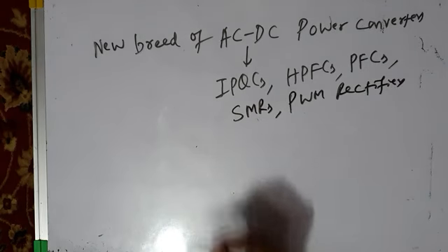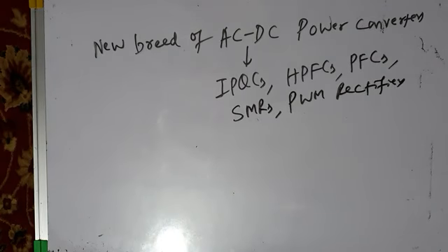All these converters do not use SCRs largely. They use modern self-commutated power semiconducting devices like power transistors for very low power range, or power MOSFETs for high switching frequency and low power range, or IGBT for medium power range, or GTOs for high power range.